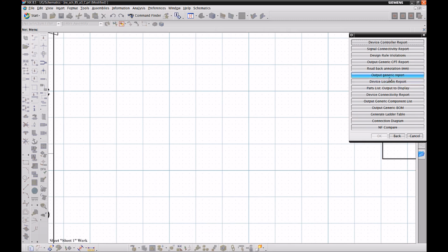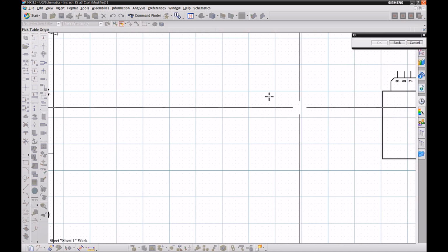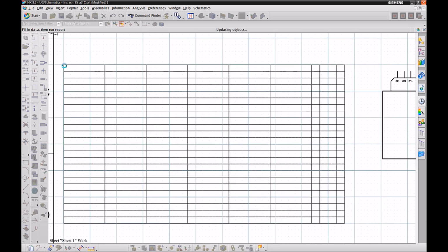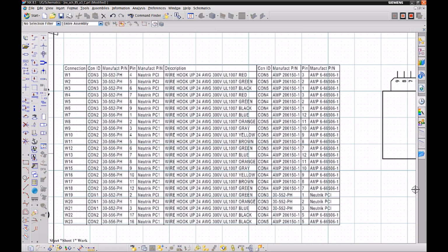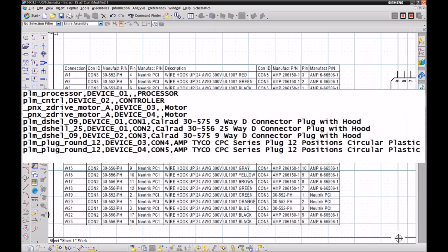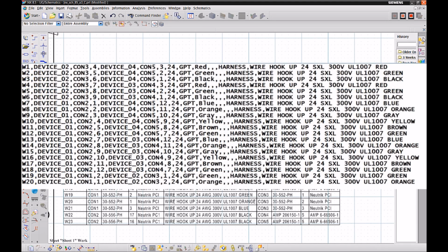Now a connection list is added. Information includes the connectors, terminals and wires with their associated part numbers. To interface with the NX electrical harness application, a component list and net list can be stored as text files ready to import into the NX electrical navigators. The import of these lists is included in the NX electrical routing presentation.